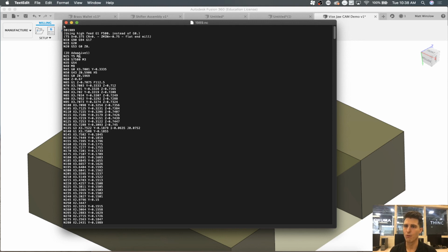Okay, I've got tool 5 doing a tool change, the RPM 7500 and G54. Just by utilizing that information right there, you can see that things are right or they're wrong. If this was saying that it was only 750 RPM, you know that you fat fingered something, and you'd go back in your program and fix it.